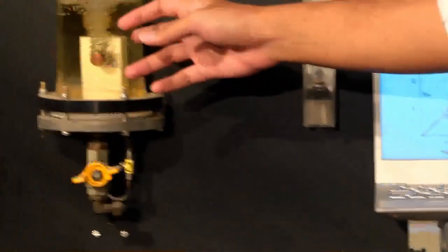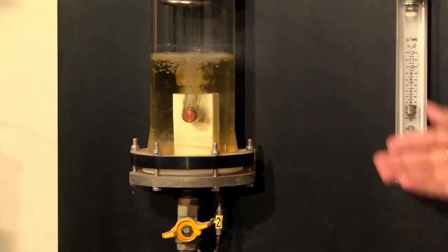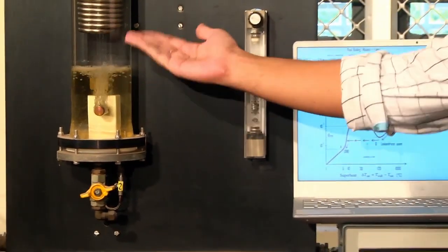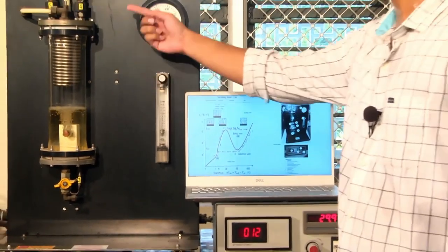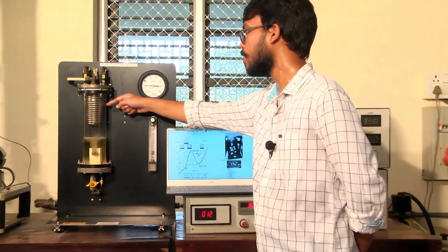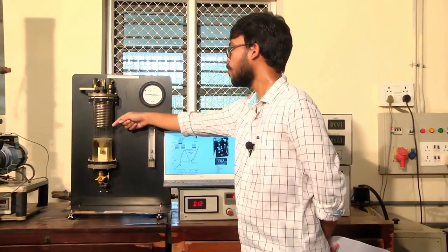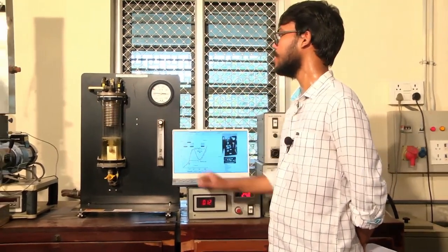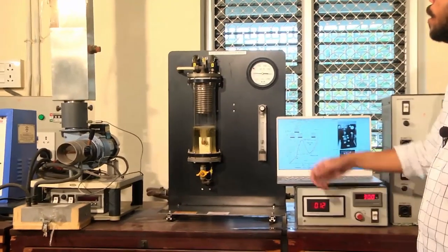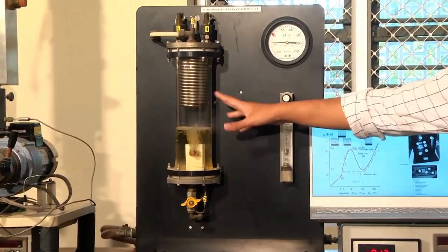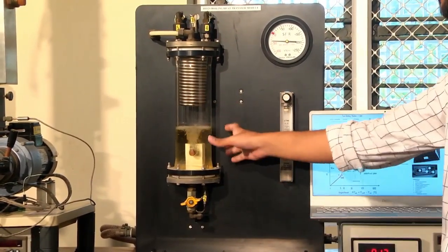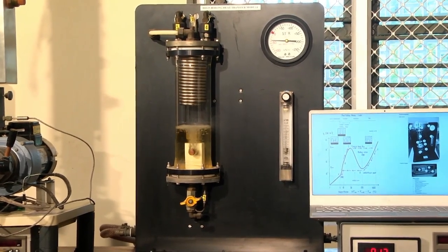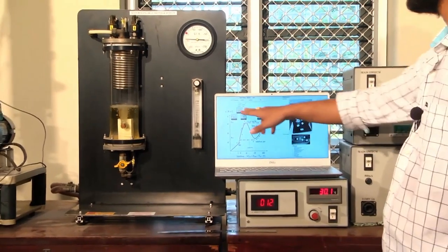This is a nucleate boiling regime, where the bubbles form and they release heat through evaporation and boiling, and the evaporated vapor is condensed here, and you can see the liquid dripping from the water cooled condenser. This condenser helps in maintaining the saturation pressure, and also it conserves the mass, so that the same amount of liquid always stays in the pool boiling chamber. And we can slowly increase the heat so that we can observe the different regimes.